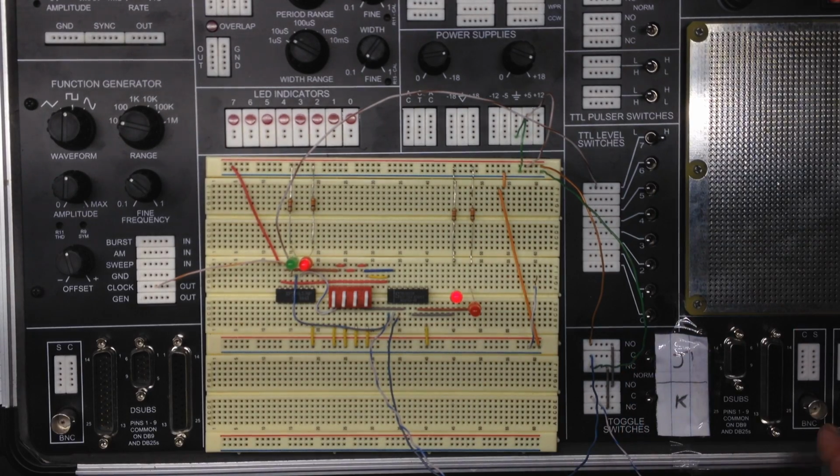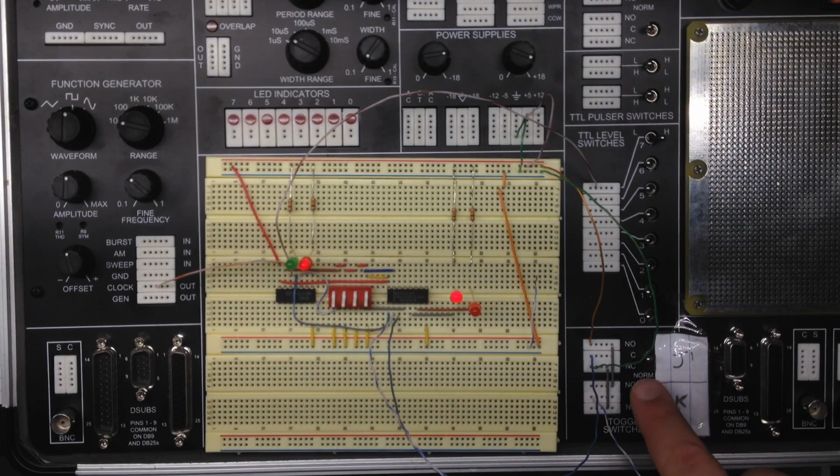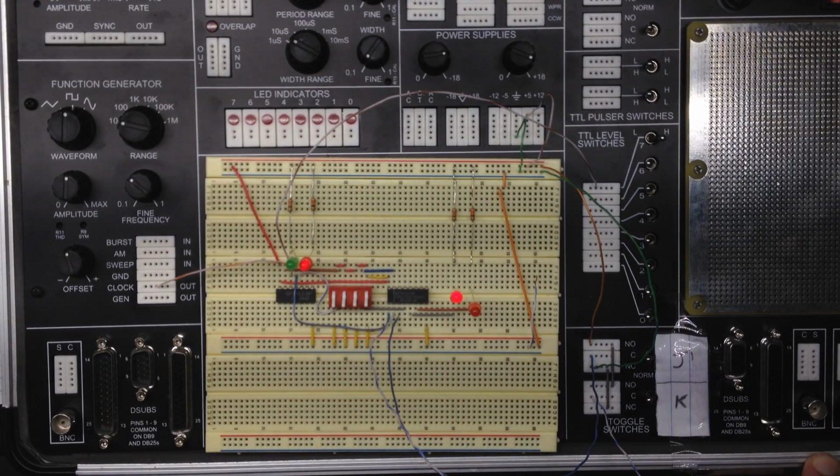So we can see that we have lows now. We have a different LED on. This is the Q output showing low, and the Q naught is showing high, and we can see that it is not changing. So this shows that the function of the logic table is correct, that the output will be the same continuously and will not change until one of the other inputs changes. The next portion of our table shows that if we have a high on J and a low on K, that we should have a high on Q and a low on Q naught.